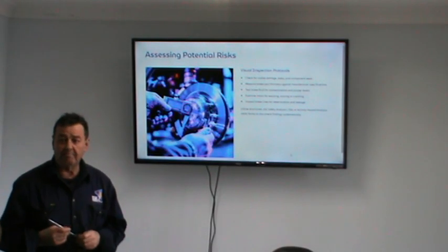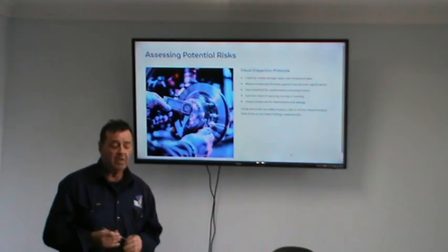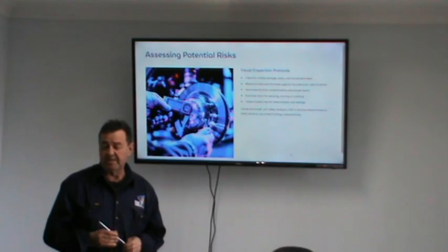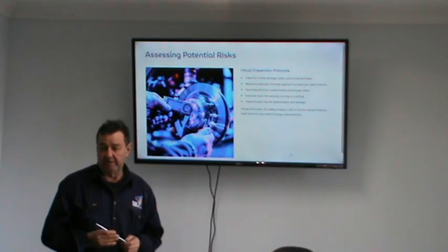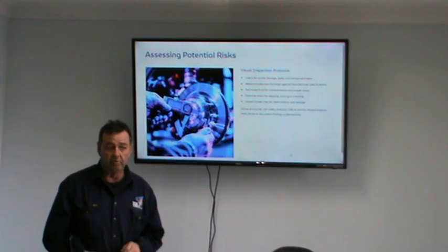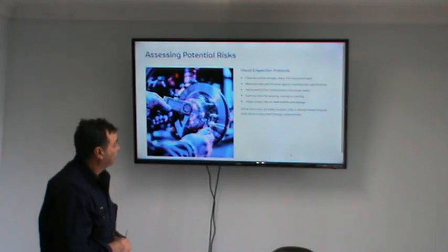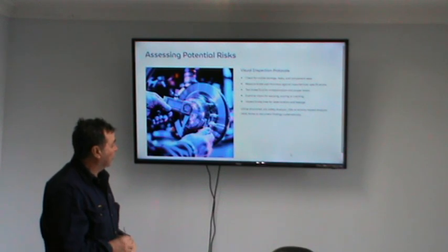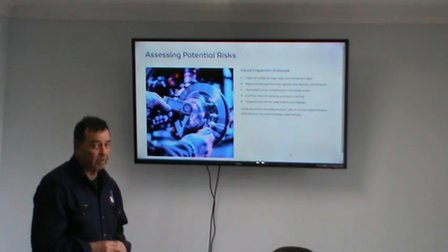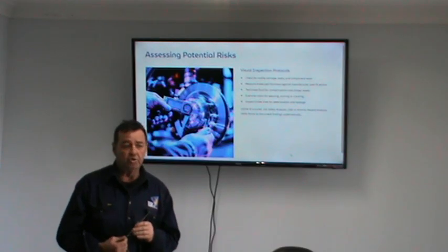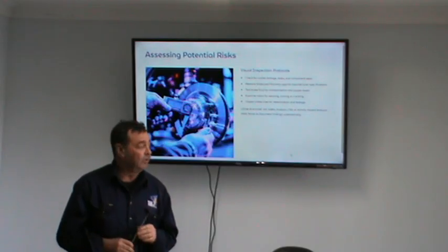If you're using a jack, make sure it's on a flat piece of ground, jacked up with safety stands supporting the weight of the vehicle, because we don't want the vehicle to fall off the stands and crush someone. When you're looking for visible damage or leaks, always wear eye protection, because some cars do have a lot of dirt and all that underneath, can fall in your eyes.